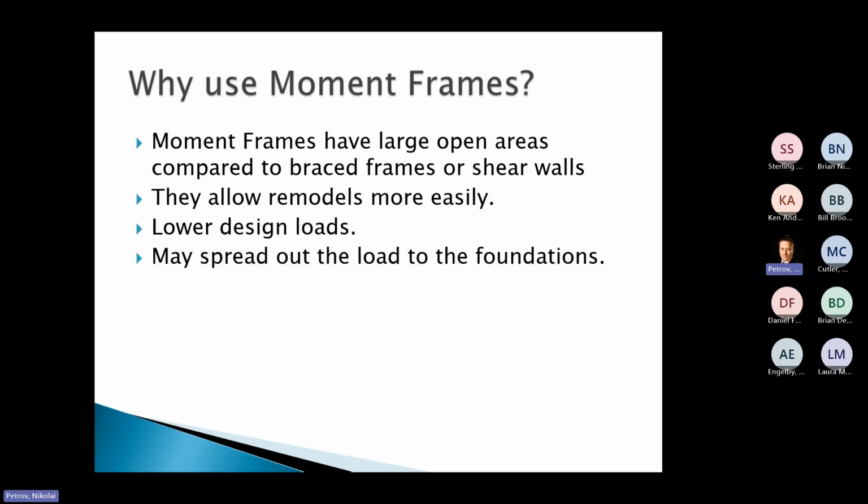More than once I've seen this happen: we have this plan of what we're going to do, the contractor gets in there and opens up a wall and says, there is a brace going right through the middle of our new OR. What the hell do we do? That doesn't happen with moment frames.